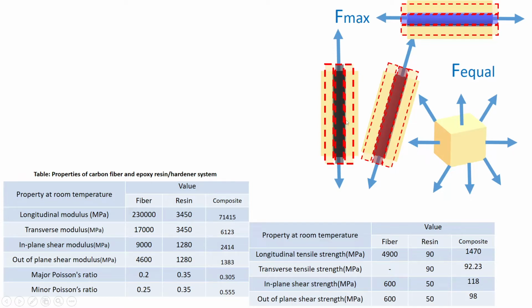So once the matrix also has that amount of strain, on the basis of the Young's modulus of this matrix, stresses will be generated in this particular matrix medium, which would then be transferred to the next layers or the fibers which are parallel to this particular fiber, and thus load would steadily be transferred.